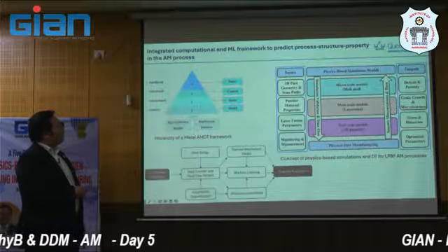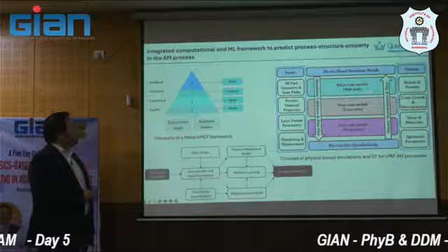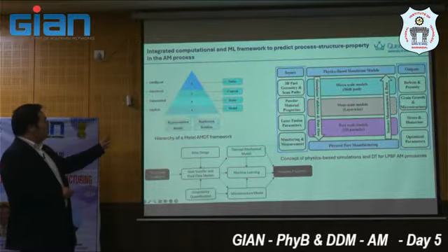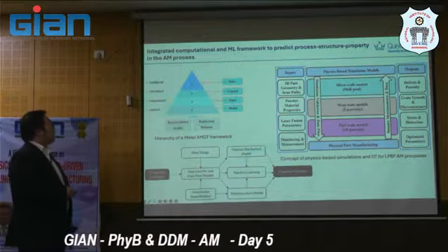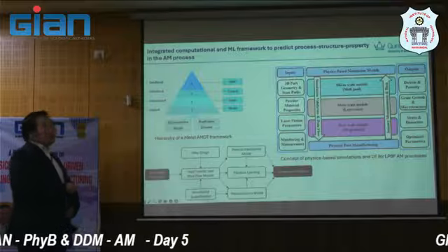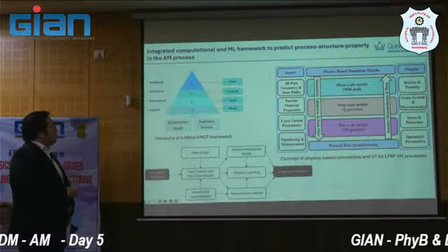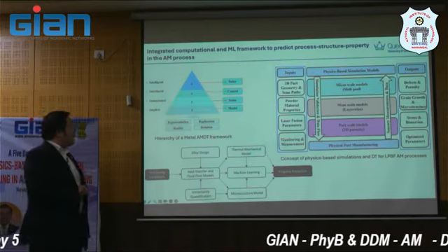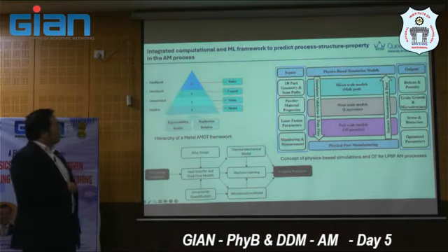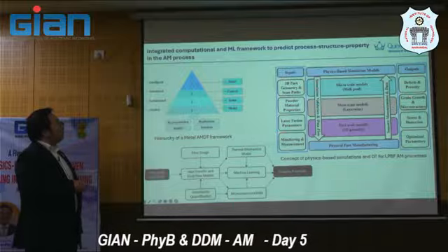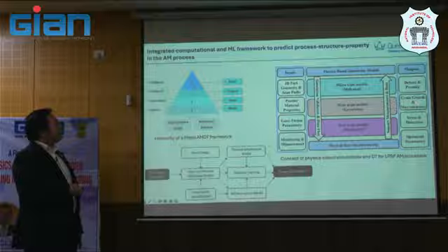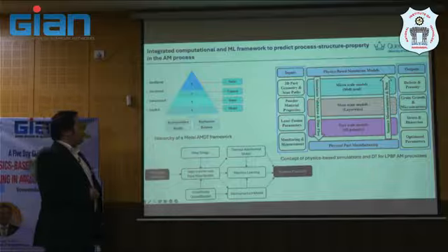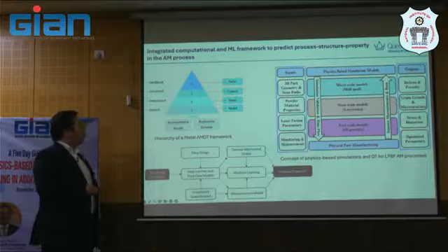As I said, this is 3D printing now in micro length scale in the melt pool, meso in the layer-wise, and then 3D printing level in the part or defect, something like that. So this may be an input: the geometry of the 3D printed part, powder material property, and laser fusion parameter, monitoring and measurement here. And output will be defect content that we said before, grains, growth, and microstructure, stress and strain distribution, distortion. And we want the output of optimized parameter.